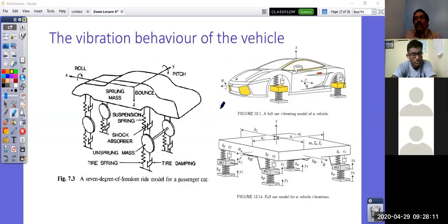So now how do you get from these models your natural frequencies, mode shapes, and so on? For that you need to get the fundamental governing dynamic equation of this vibration model. That can be obtained by Newton-Euler equation, when you have coupled translation and rotation, or you can also get it by applying Lagrange equation with the dissipation model. That is a popular one, where the Lagrangian is the difference between kinetic energy and potential energy. And you have that set of Lagrange equations which you have studied in your fundamental vibration course, or you can refer to Jazar's textbook. You have Lagrange equation applied to derive the governing equation.